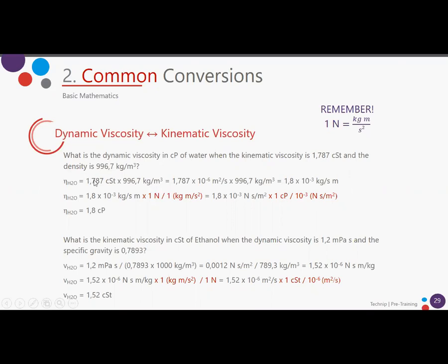So what I do is I multiply the kinematic viscosity with the density. And in the next step, I also convert centistokes to square meters per second.